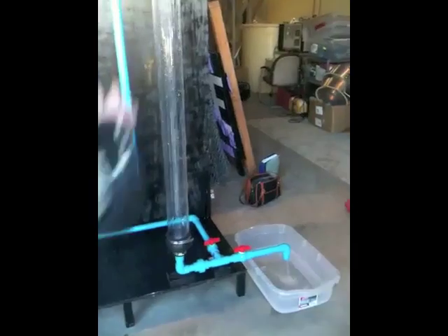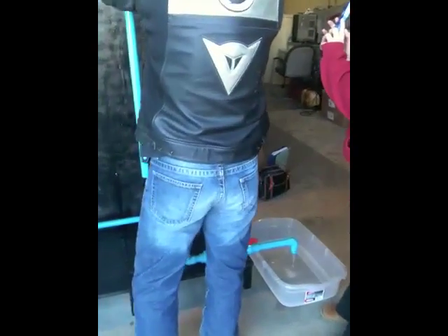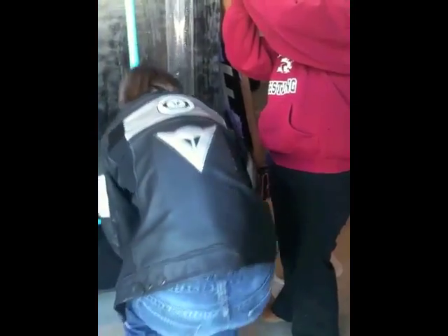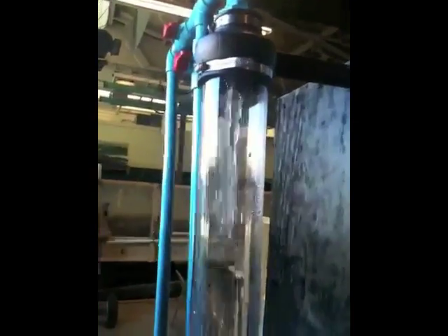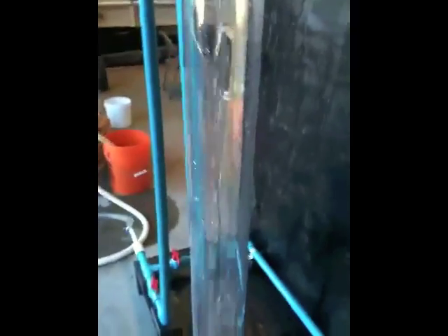The column used for the resin has a 4-inch outside diameter and 3.75-inch inside diameter. The 1-inch to 4-inch expansion for the connection of the water pipe to column was accomplished with a rubber coupler. This, along with a threaded joint at the bottom of the column, allows for easy removal. Nylon mesh was put in between 2 metal drain plates and serves as a diffuser and a filter to hold the resin inside the column.